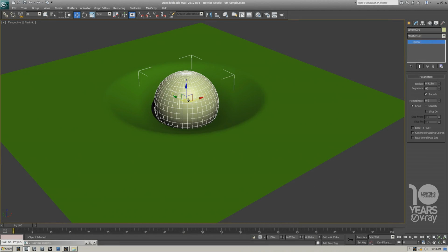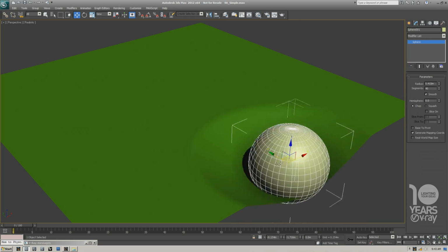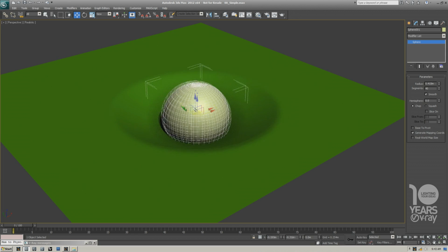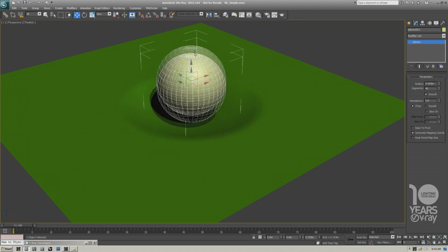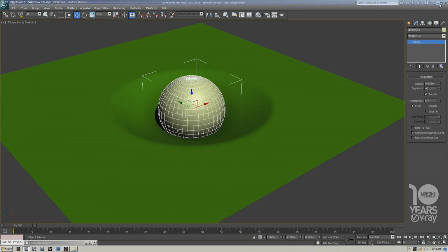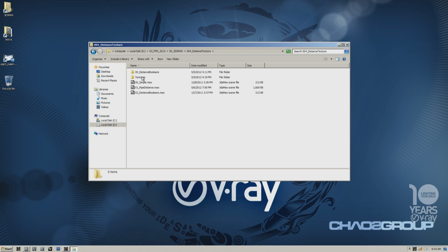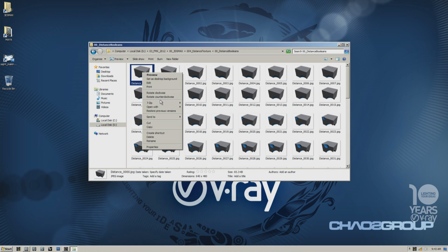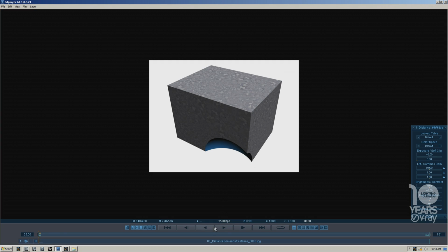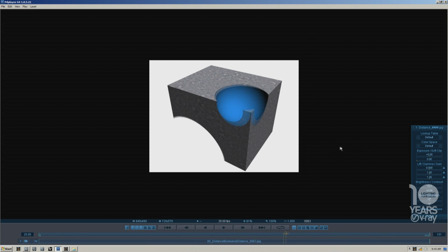So if I activate the 3ds Max displacement of this plane, you'll be able to see that it's displaced based on the distance from this sphere. So quite a handy effect, and if you're creative, you can create really interesting things with that. For example, I used this same texture in order to get real-time render time Boolean operations. And I'm using the texture as opacity, and if you link it right, you can get this sort of effects.